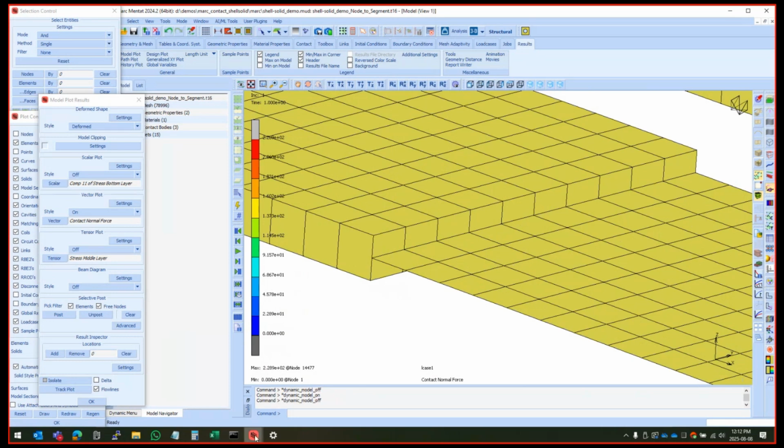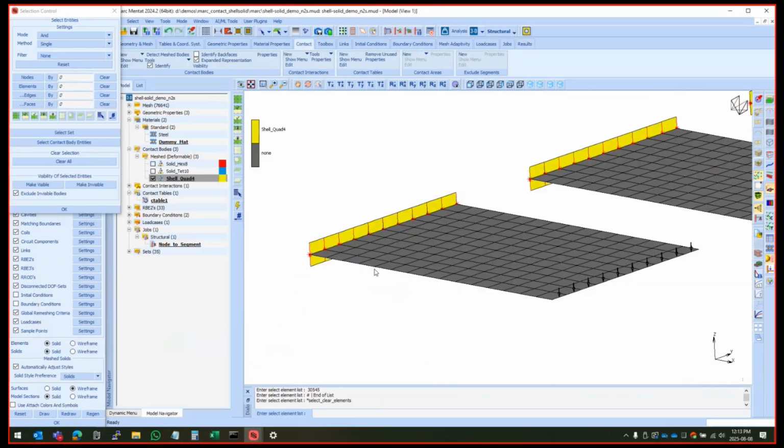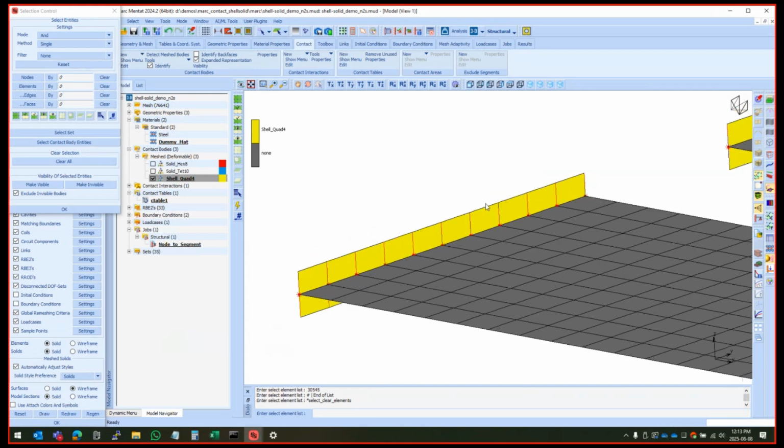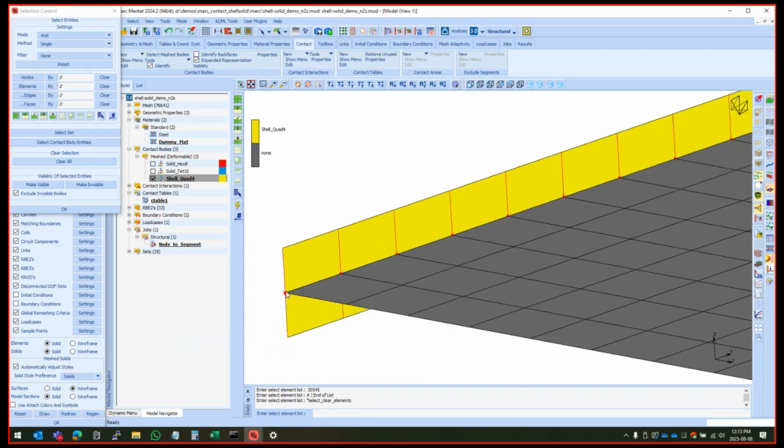Okay, so if I switch to a model that I use just to explain what I'm actually interested in, if I create the skin shell mesh over there and I've picked them so that there's a single element, that's not one and one, it's one single element to show that that's one element. And I rigidly connect the corner node to that center one. Then effectively what it says is the motion of that node determines what's happening at those two locations. I then define a very low stiffness for this element.